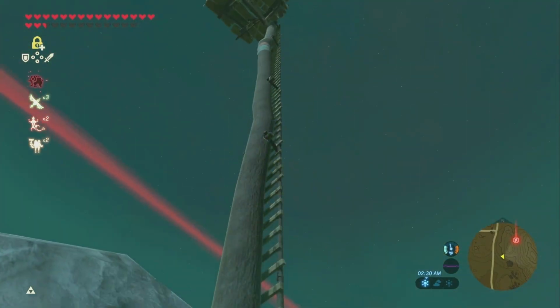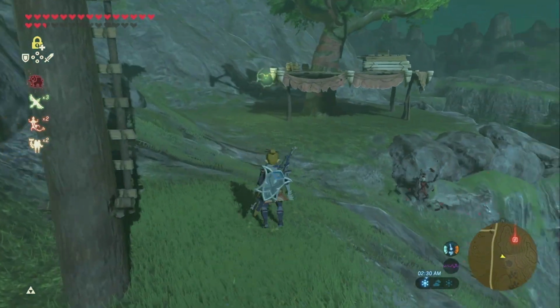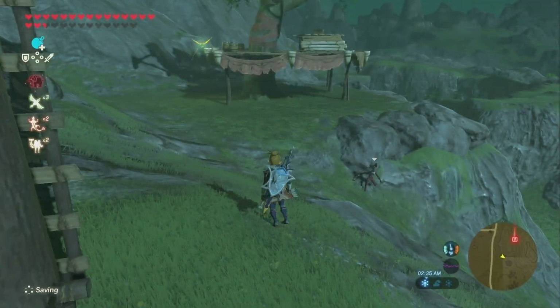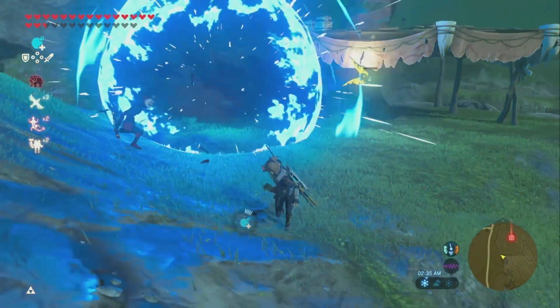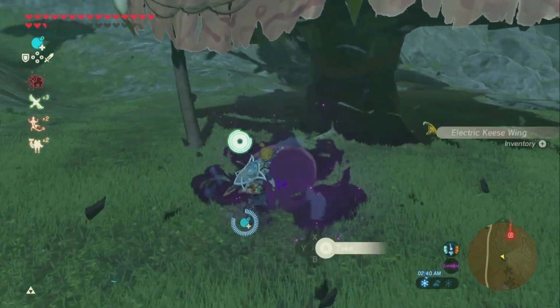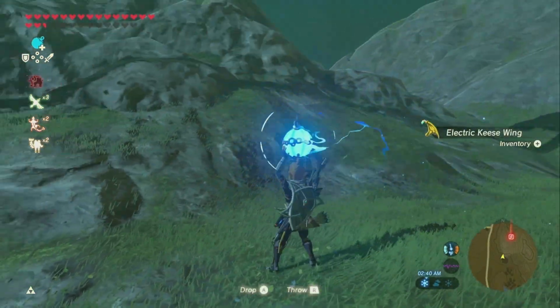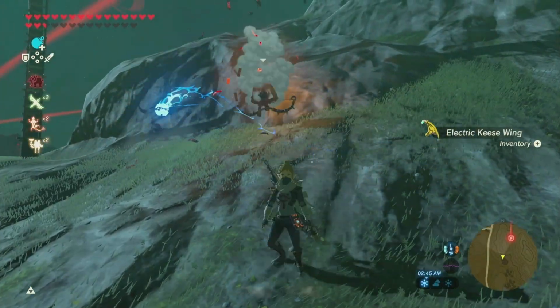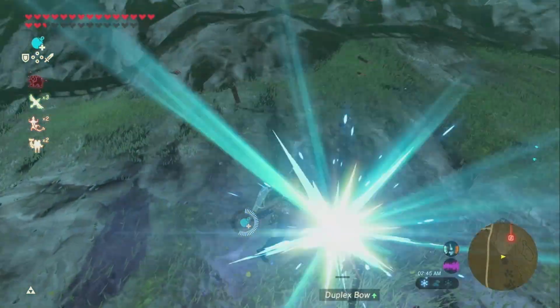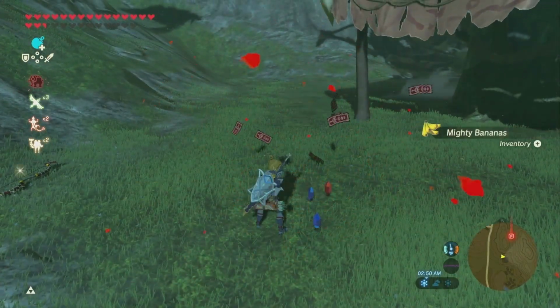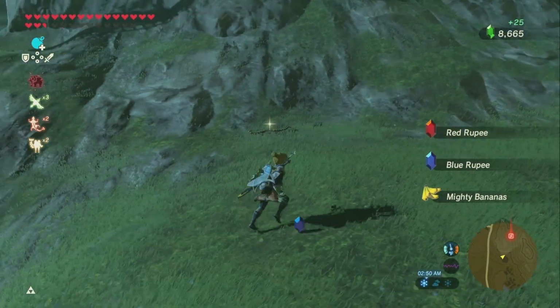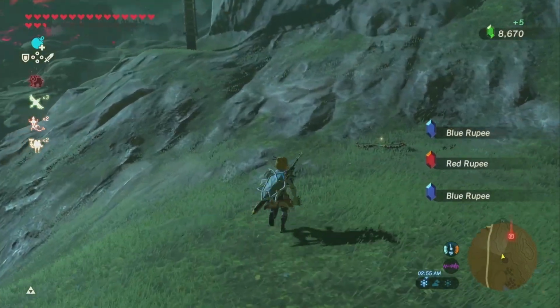Many others, including Rehau, Vanguard, Uponor, and Apollo, I'm guessing these are names of brands, say it has to be 18 inches away. The UPC, Uniform Plumbing Code, says PEX tubing must be 18 inches away from the water heater.